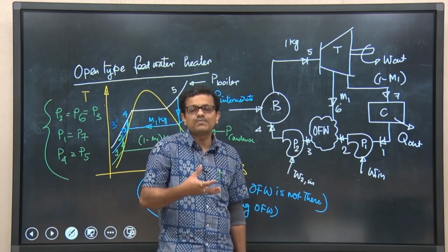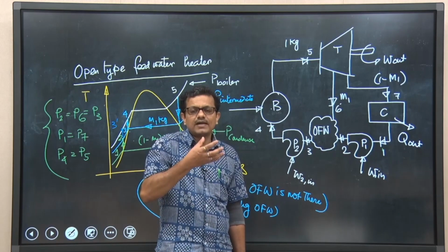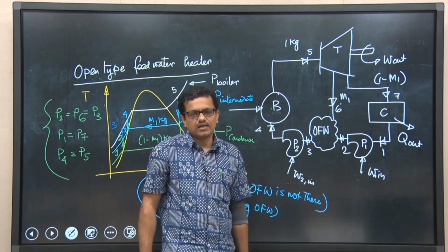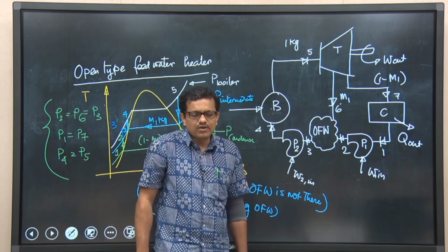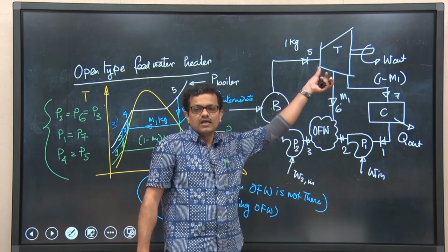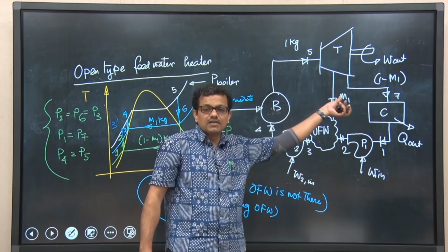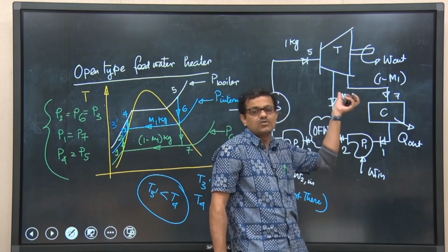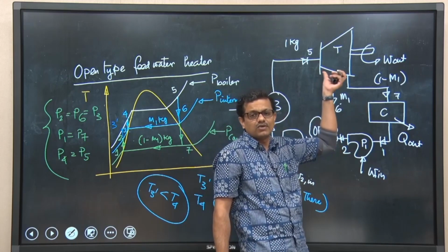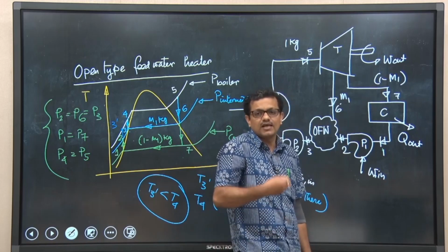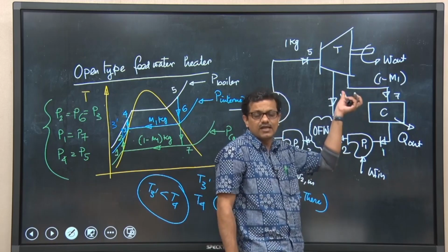Instead, this is coming from taking some amount of heat from the flowing steam inside the turbine. We should be careful that since we are extracting a certain amount of steam from the turbine, this fraction should not be a substantial amount of the total steam flow rate, otherwise W out would be compromised. So, we should be careful while extracting steam from the turbine.